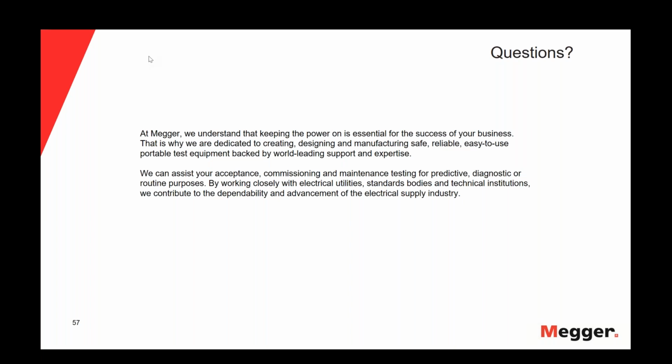All right, thank you. Robert, what is the difference between EPR and XLPE? Well, a chemical question. Okay, the principal difference is that XLPE is a pure insulation material, and EPR is a so-called filled insulation material. On a chemical level, EPR belongs to the class of so-called copolymers, and it's called a copolymer because you use two basic structures to create the chains and then the cross-linking. So you have ethene and propene. This is why it's called ethylene propylene rubber. And XLPE is just a cross-linked polyethylene.